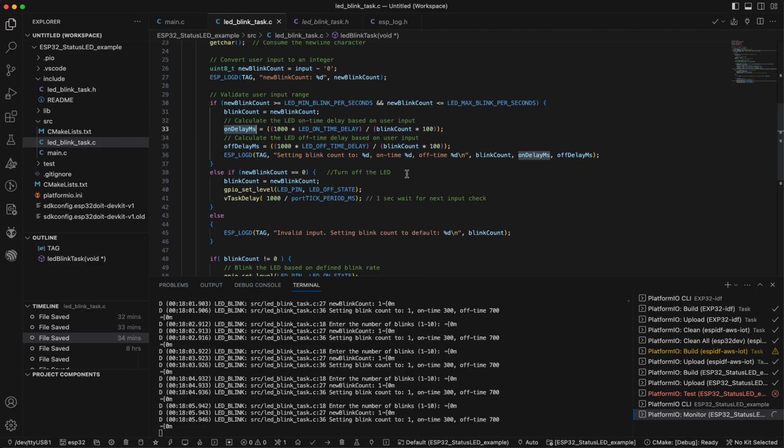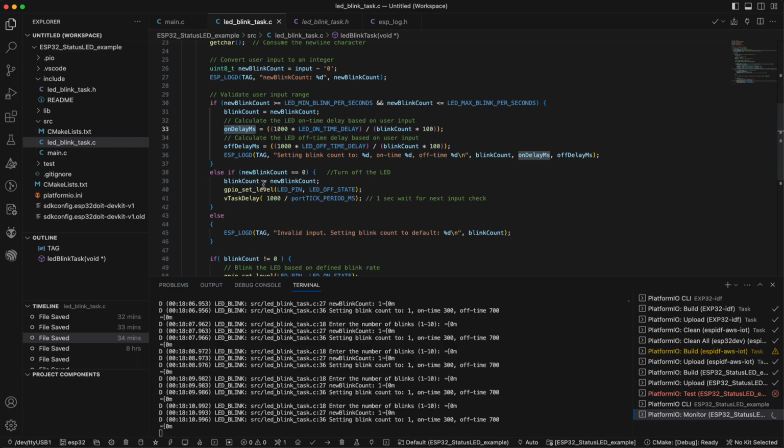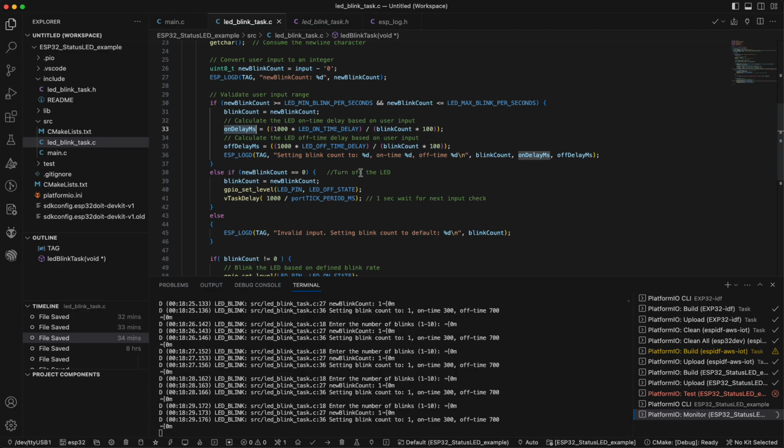When there is a state change, only then you blink for some time, say 5-6 seconds, to indicate the state change happened, and then you turn off the LED so that you can save some power. That is where I made a provision so you can turn it off, and then you can keep on changing it.